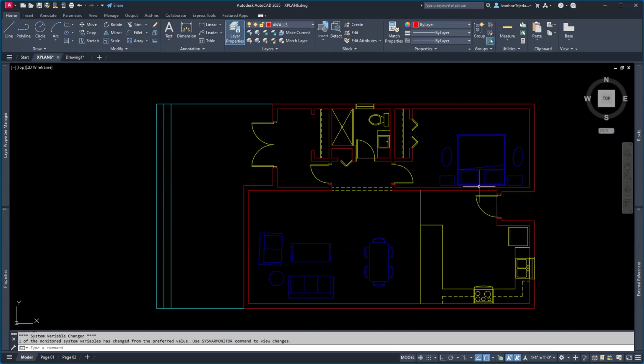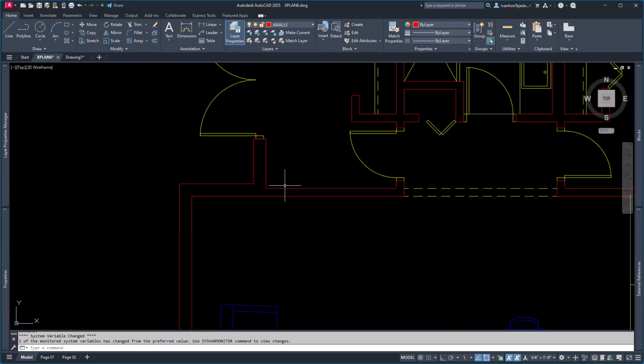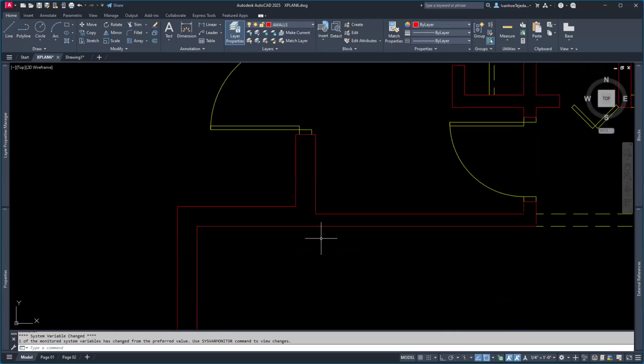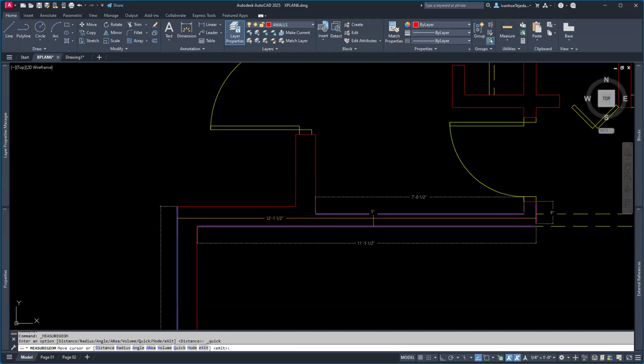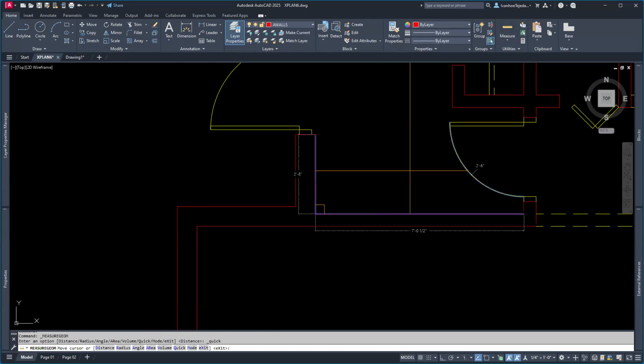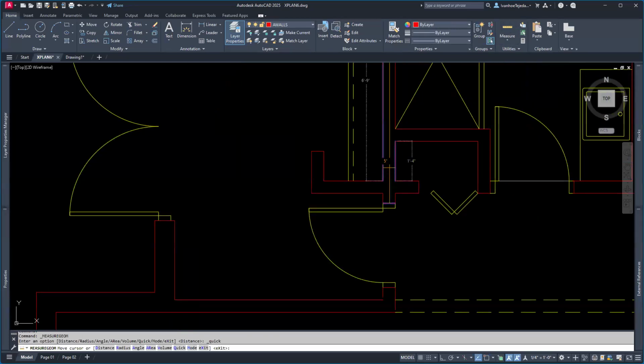I'm just going to put this one in for now. And like I said, you'll have the bathroom plan to use. You'll need to explode it, but you will need to put in the walls as well. So over here, it gets real interesting because this is an 8-inch wall, but when we come to the inside, the interior walls, let's see if I can measure those. Yeah, they're going to be 5 inches. So if I move over here, you'll see 5 inches on the interior walls.